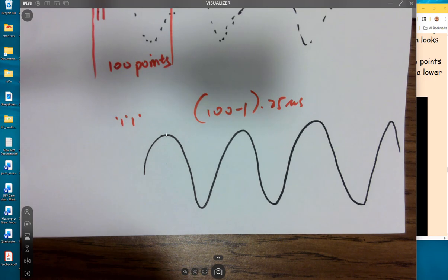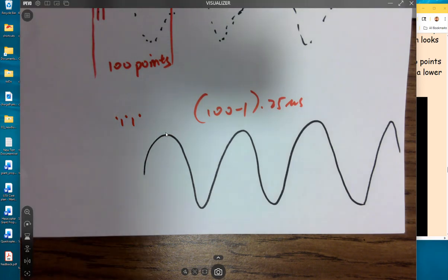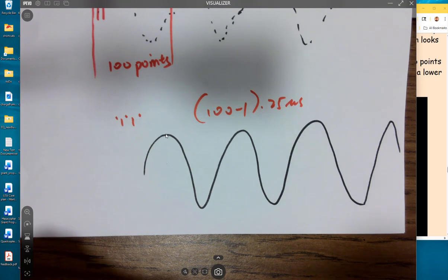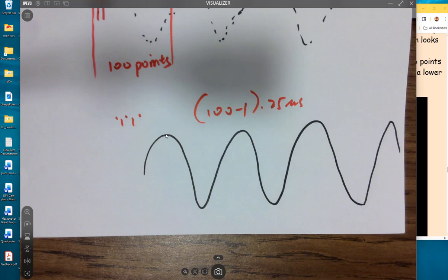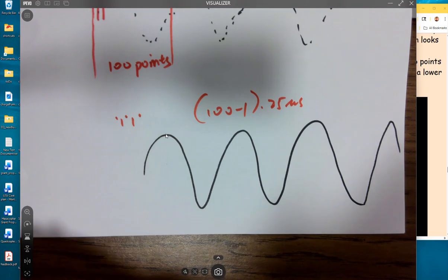If you are detecting peaks, you could compare with the previous one, like I minus 1. Because everything is stored in the buffer, you have all the i's as index. So if you look at the current value I, and I minus 1 and I plus 1 are both smaller than I, right? That's going to be a peak. I think that should work probably.